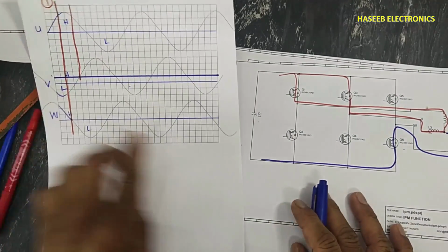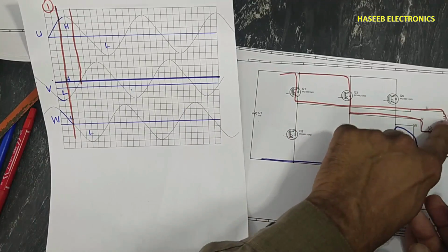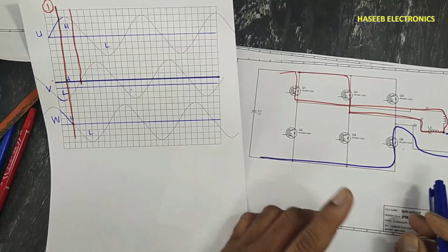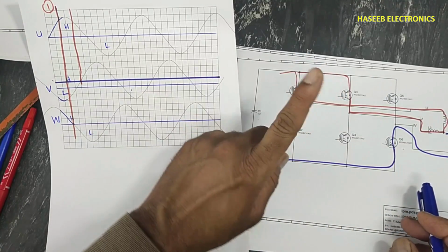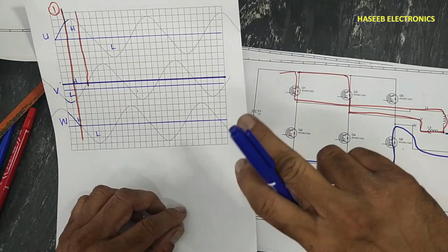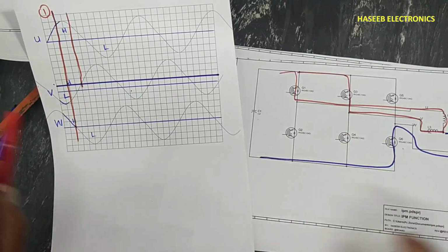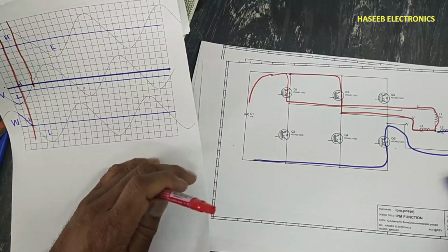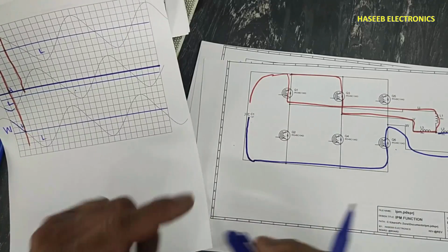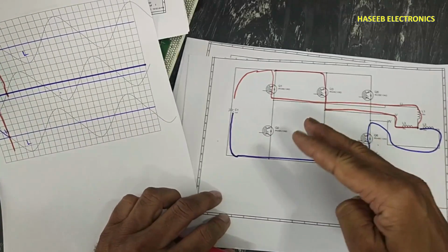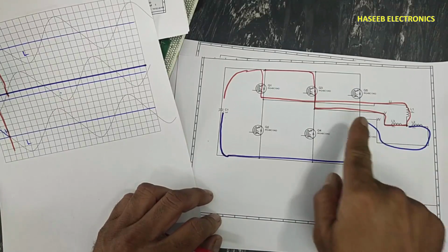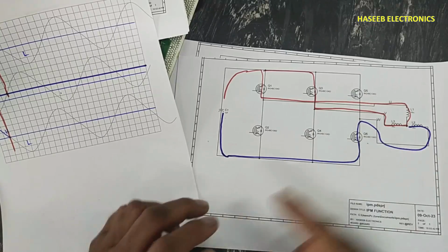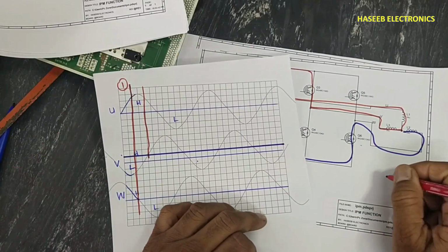Now we can see current flow from this IGBT, this winding, and the return path now from this winding. Now the magnetic field will change. Before this here, now here, now here. The resultant magnetic field will change, and the voltages coming to this power capacitor DC rail will be switched from time to time in different windings, so that each winding will change its magnetic field step by step. This is our step number 3.